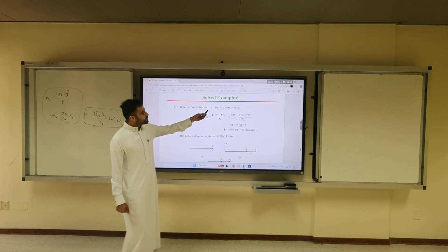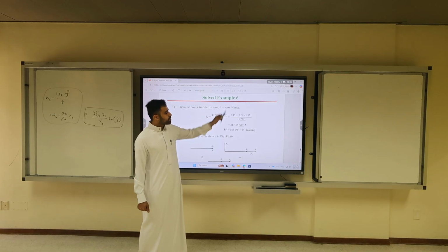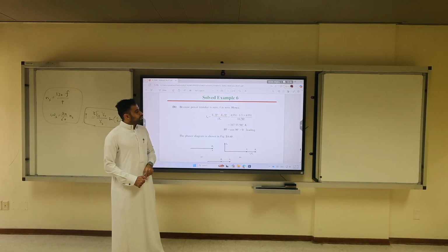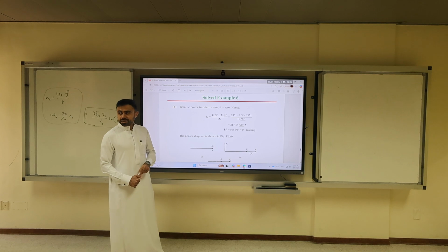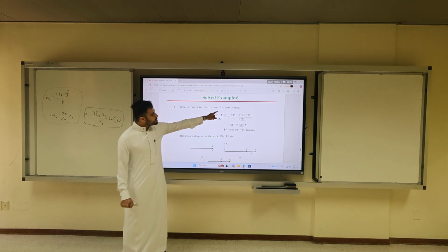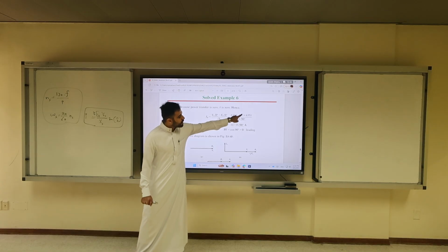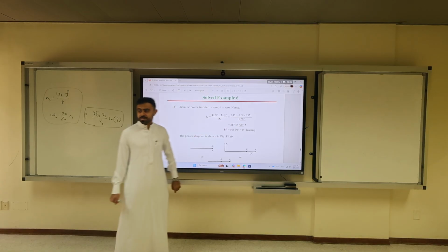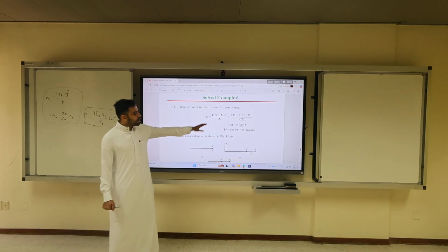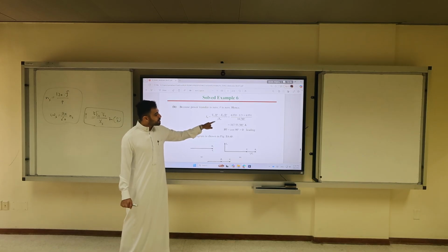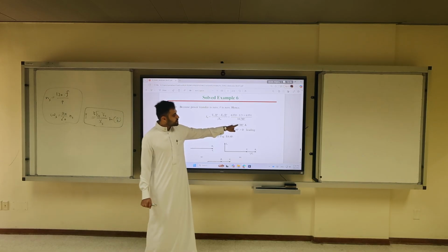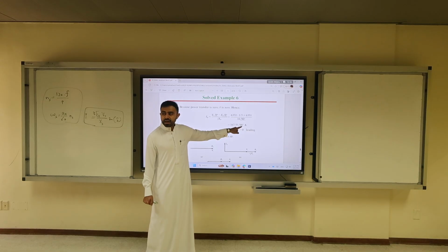Now, how to solve this problem is very easy. Because the power transfer is 0, we have delta is 0, so the torque angle is 0. If the torque angle is 0, I substitute Vt the same, 6351 minus 1.5 times that. Both of them are in phase. Divided by jXs, and now I get a new Ia, which is at 90 degrees. Ia now is what? 90 degrees. So this is a pure synchronous condenser.